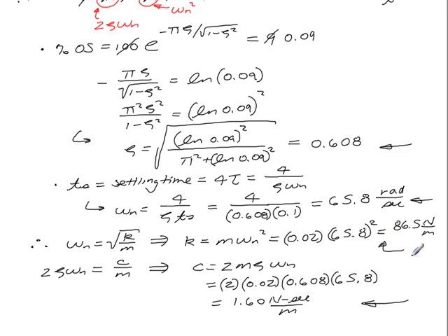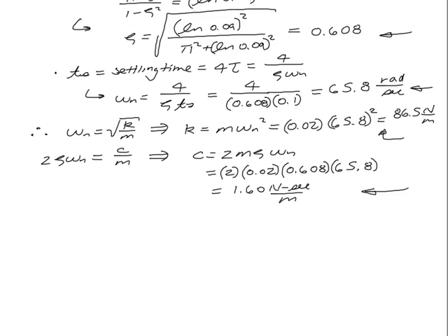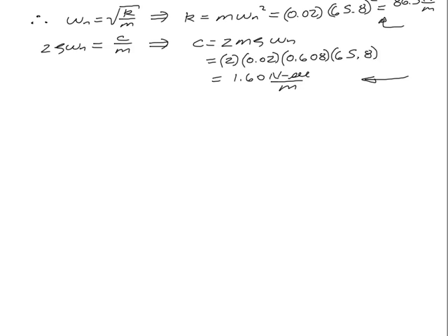So these results that we used here, the equations for settling time and percent overshoot, you might recall were based on understanding where the poles were in our complex plane. So let's make a sketch of what we had there. Let me draw out the complex plane here, real and imaginary parts. So this axis here was the real part of our pole, the imaginary part on this axis.